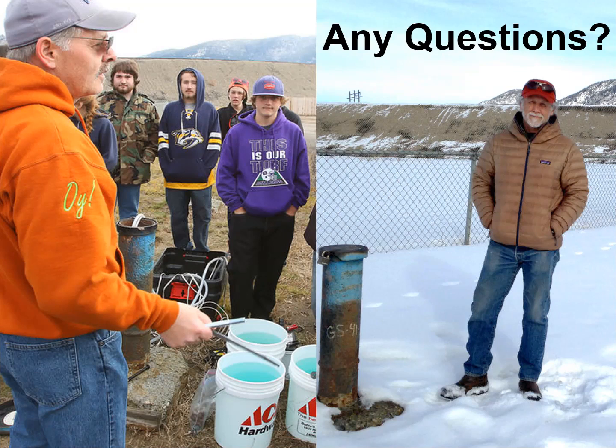So it combines copper that is adsorbed onto particles, and it also includes dissolved. And Doug's question really gets at a big question, in that the state uses total recoverable as a standard. The EPA uses the federal standard, which is simply dissolved or a filtered sample. And there's generally a pretty big difference between the two in stream.